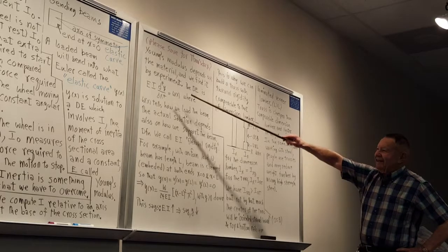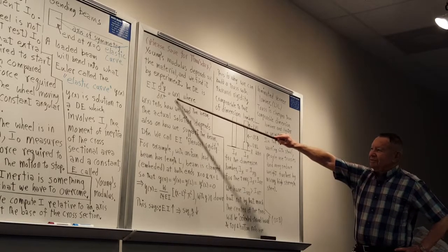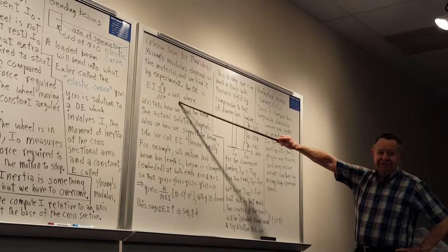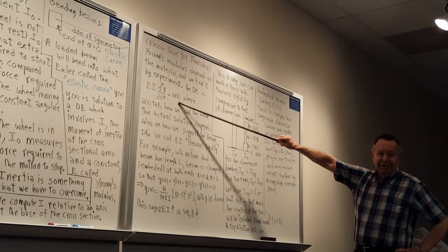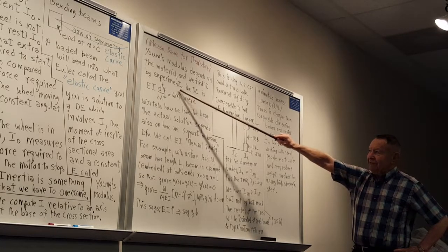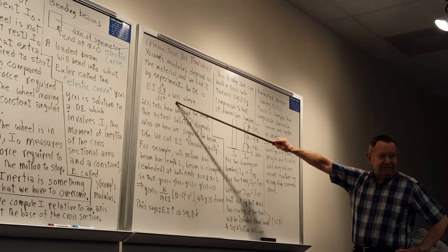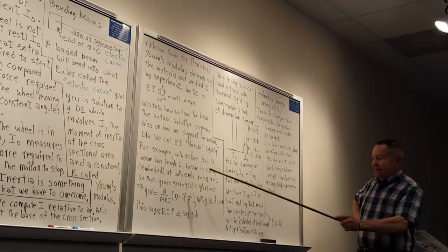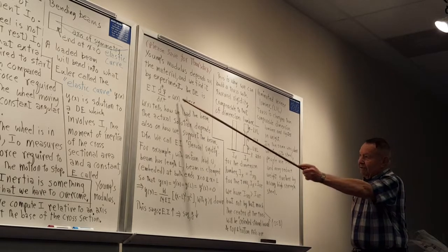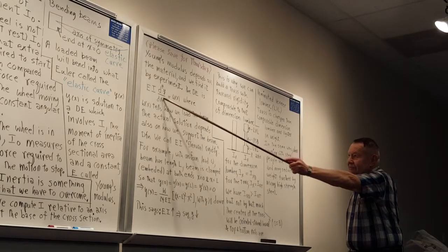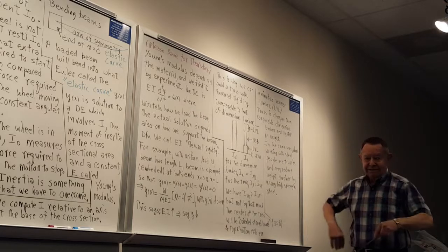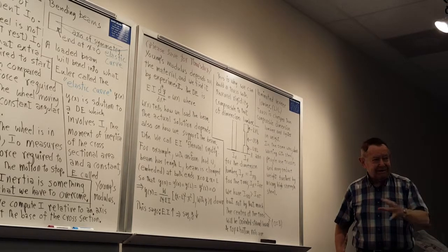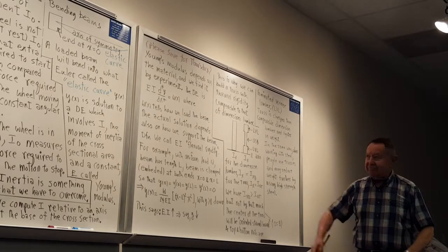Anyway, then this would be a function that's how the beam is loaded. And so you'd have to make an assumption about this or have some way to know from experiment. When you're solving a fourth order differential equation like this, you see you're going to integrate 4 separate times.